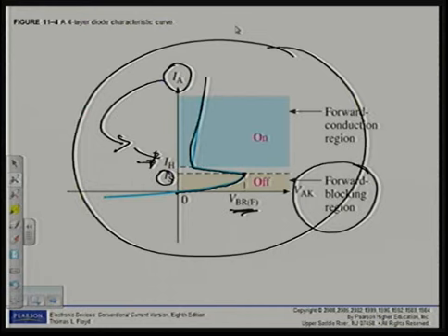At the bottom of page 555, they discuss the holding current as well, and the switching current. You can have a read through, and then on the next page, page 556, example 11.1: a certain 4-layer diode is biased in the forward blocking region with an anode to cathode voltage of 20 volts. Under this bias condition, the anode current is 1 microamp. Determine the resistance of the diode in the forward blocking region. Normal Ohm's law to do that calculation. So look at the other examples as well.